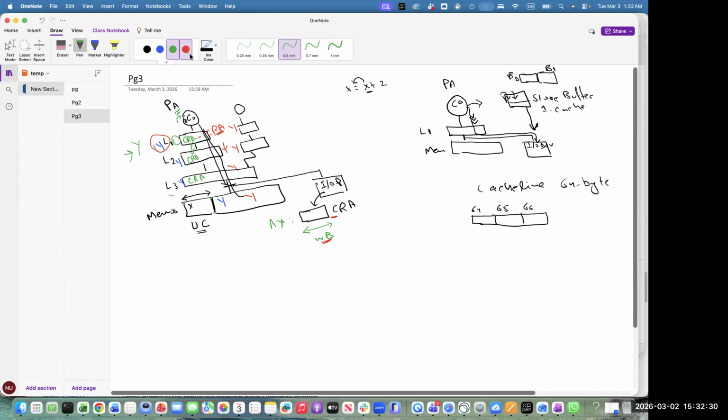But in case of write through, when you are updating it at L1, you are also updating it at L2 and at L3. So yes, you are occupying the space, but the data placed in the occupied space is the valid data. So you are not polluting the cache. You contain the valid data in those cache hierarchies.